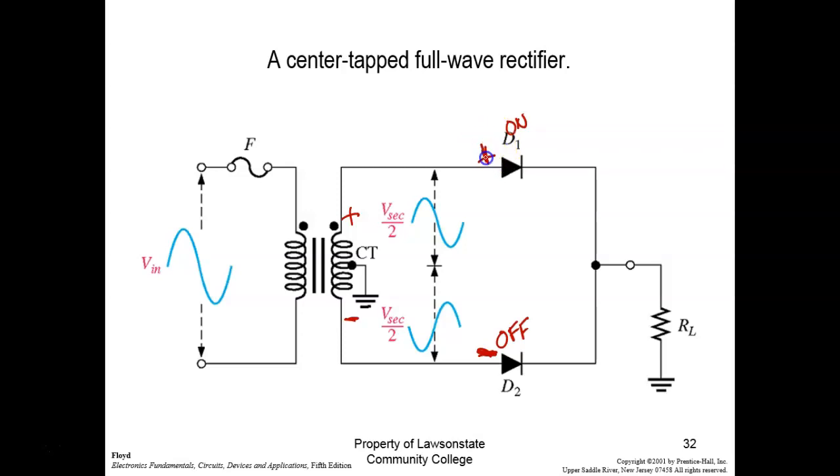Here I have a positive on the anode. Okay. Relative to this side over here. Well, what's this side over here pointing to? It's pointing toward what we consider to be 0 volts. So this guy's pointing towards 0 volts. It's not going to be there. So 0, because we have the resistor, right? You understand? So it's not going to be 0. It's going to be 0.7 of a volt less than what this is.